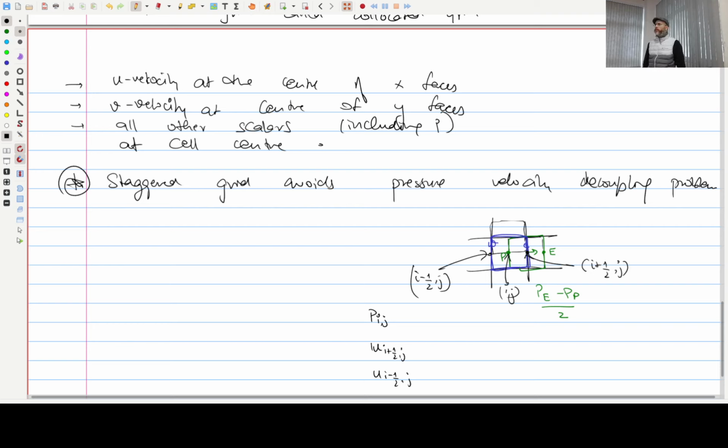I had all this discussion with you because I would want you to know this, since this discussion will come up if you work with CFD. But most of the solvers nowadays are using co-located grids again. The choice of grid is still the same, but we have modified our methods. Ultimately, what we were doing was to get the value on the faces using linear interpolation. If you use some other kind of interpolation that allows communication between alternate points, that is also valid. Ultimately, we want to avoid the alternate discussions; we want to have adjacent discussions. So if we have a method that allows adjacent points to communicate, that's good enough.